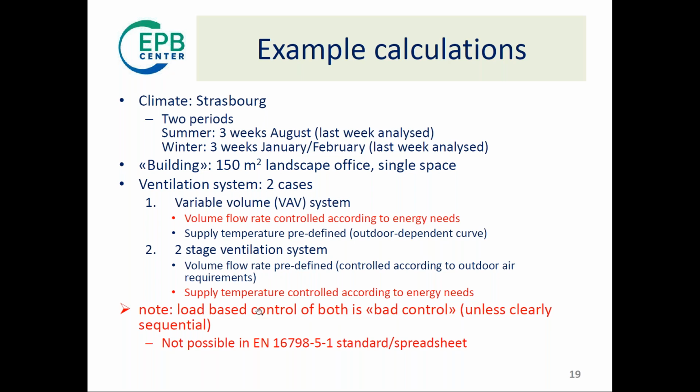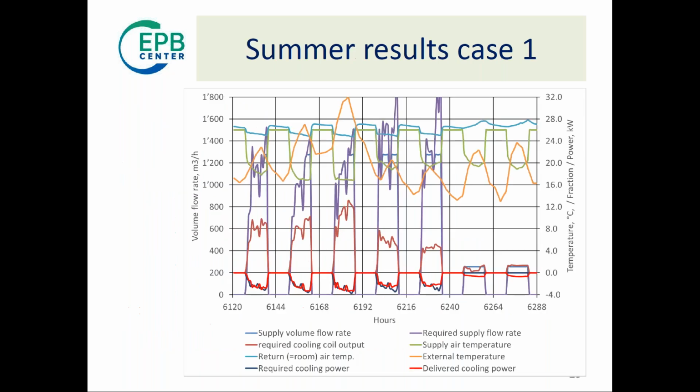Well, I have to note here that the load-based control of both is actually what you could call bad control. There is a way out. If you do it clearly sequentially, then it should be possible. But it's not possible with the current EN 16798-5.1 standard and spreadsheet.